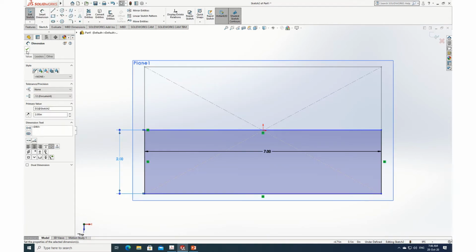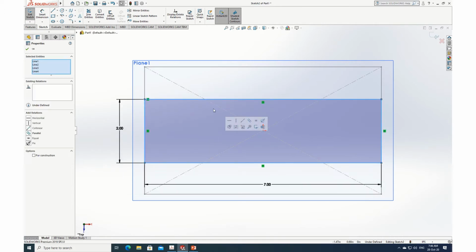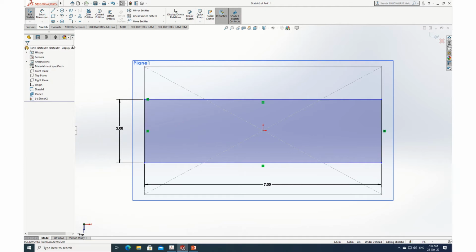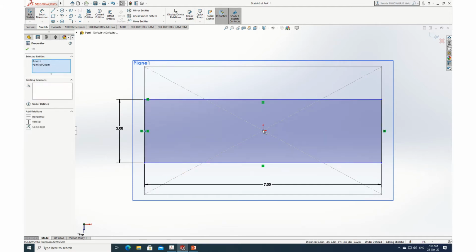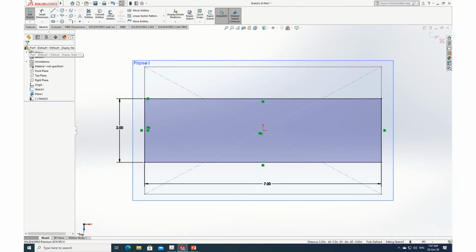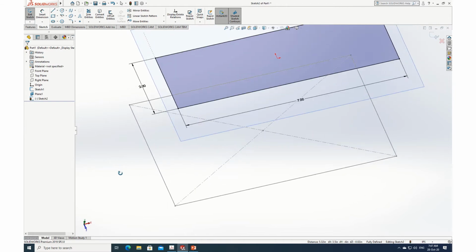See, the size became small now. Okay. Now let me move up and down. So how do I fix it? I have to fix it. So what I will do now, I will select this line. When I select this line, I will find the center of that line, the midpoint. Then shift-select this one. I will make them stay on a horizontal line. See there? Now I am already there. You can move up and see I am already there.